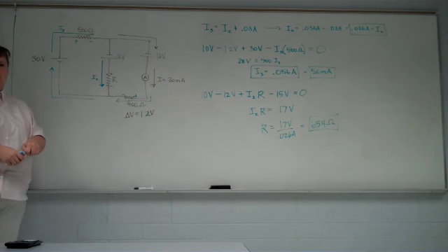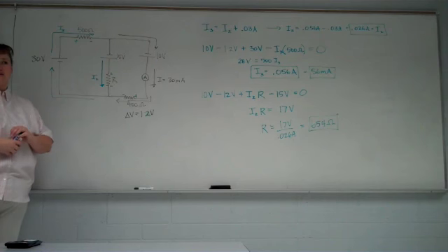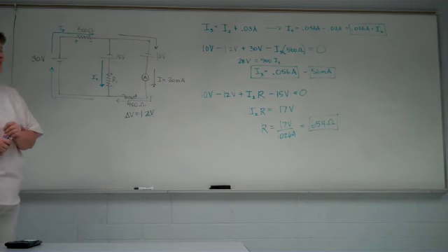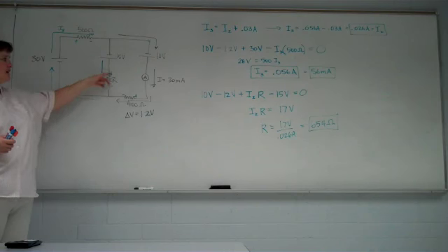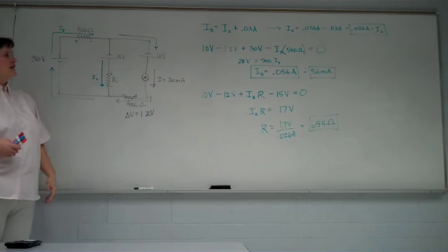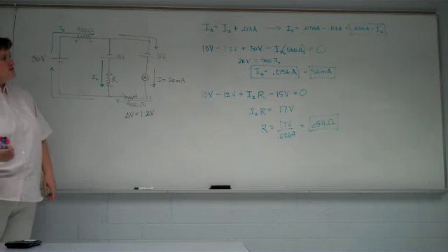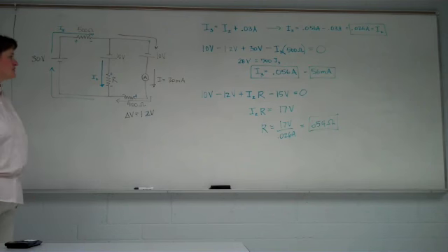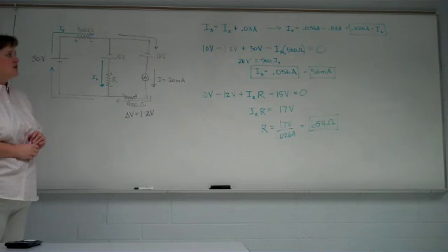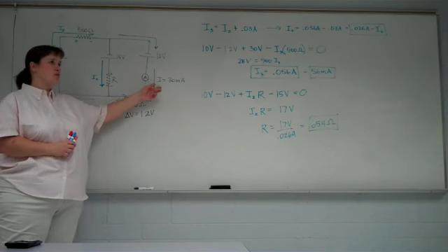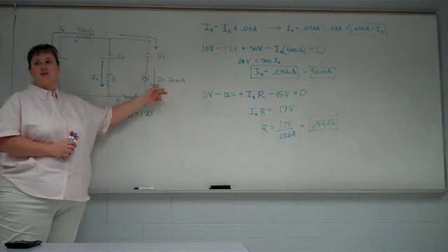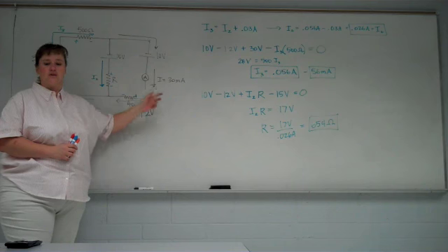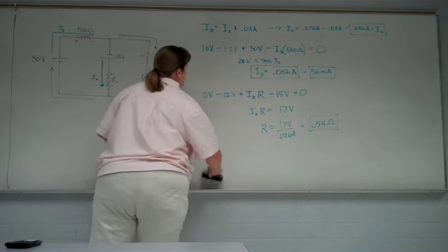Okay. Any questions on how we got any of the equations? It's a matter of remembering it. So the process is drawing in your currents, figure out high and low for your resistors, and then write some equations. Write out your junction rule, write out a couple loop rules. If you're given current and you've written a couple loop rules and none of them are easy yet, write the third one. Because if you're given a current, one of the loop rules is going to be nice. One will give you only one unknown, like this one did.